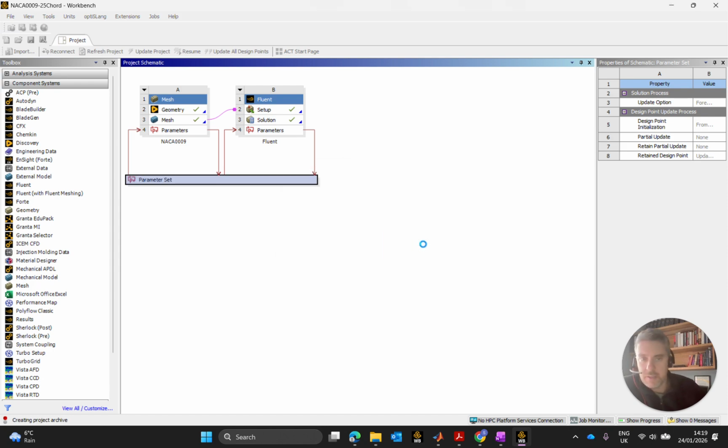I don't have any imported files. That's generally maybe your geometry files, or maybe you had a meshing file that you brought in. We did everything within ANSYS. So I could tick that anyway. It's not going to make any difference as such. However, if you did import a STEP file or a Fusion file or Inventor or SolidWorks file in for your mesh, and you wanted to keep that, yeah, keep that ticked. So we're just going to keep on working onto this one here.